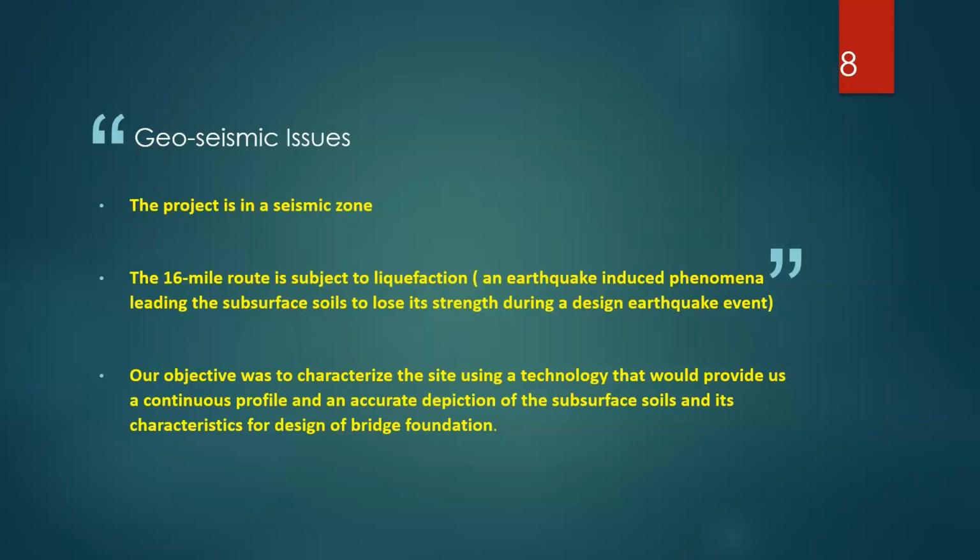If you're in California, or for that matter in seismic states in the United States, you have to deal in your projects with geoseismic issues, the impact of earthquakes and their geoseismic aspects on the design of your foundations, your bridges, and your geotechnical assets. This project is in a seismic zone, and it was subject to liquefaction, which is an earthquake-induced phenomenon that leads the subsurface soils to lose their strength, their shear strength, during a design earthquake event.